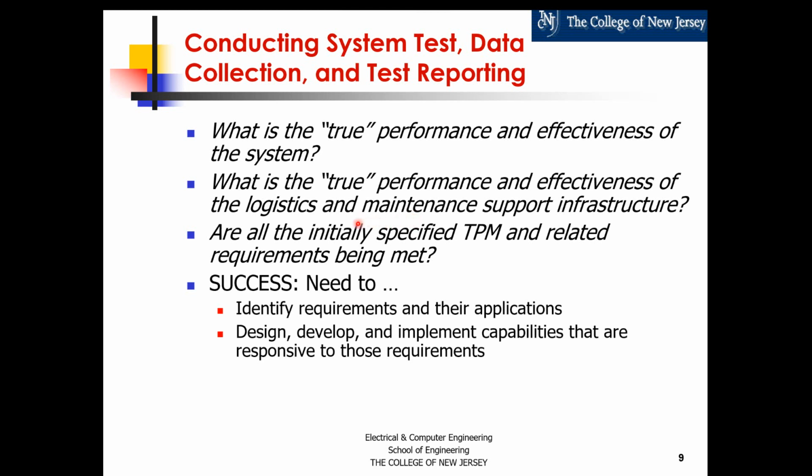You can get a lot of statistical data and look at distributions and a statistical analysis and metrics of the technical performance measures of the system. Are they really being met? What type of accuracy and precision distributions do you have? What type of control on those distributions are your manufacturing processes yielding? You cannot get this from the initial development and design stage. You have to have enough of what we call pilot runs, where we build anywhere from just a few hundreds of a product, and that's enough to get some meaningful statistical data on things like TPM distributions and things like that.